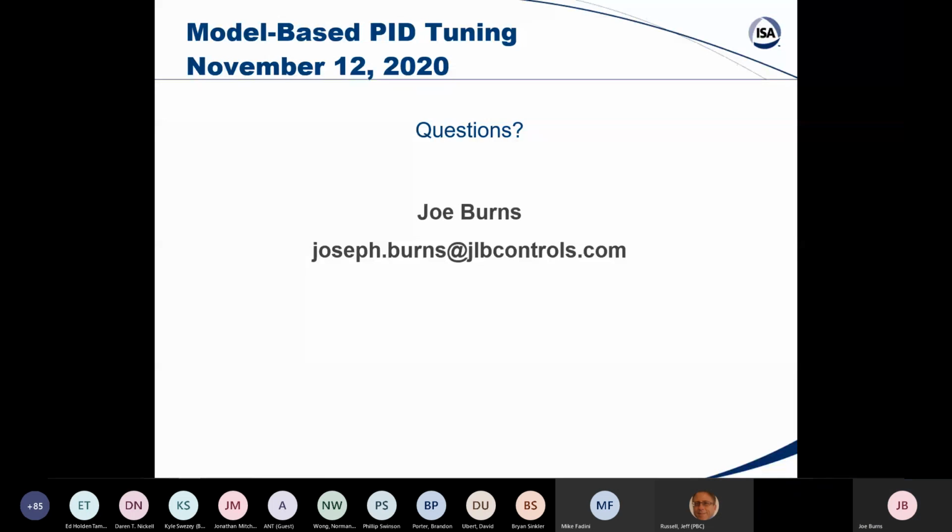One of my experiences is that when you bump the output, depending on the loop gain, you really got to bump it 5%. 1 or 2% often just doesn't give you any feedback due to hysteresis in the valve. And then you compound the problem with the owner not wanting you bumping his process 5 or 6%.